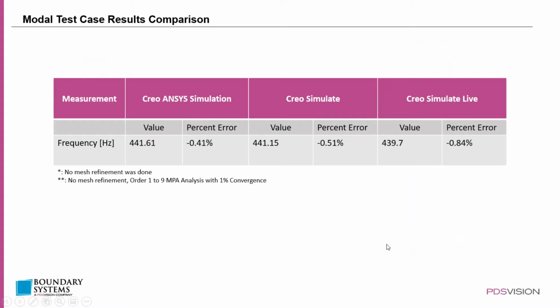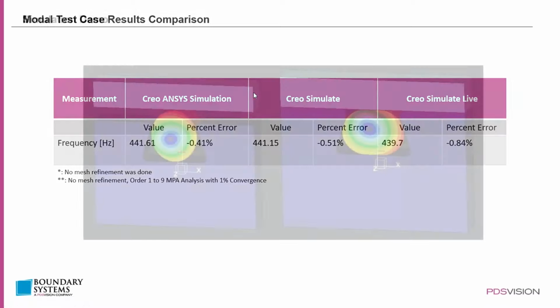And here, what we actually interestingly enough see is every software is very accurate at calculating this modal frequency, which points to the fact that for modal analyses, if you're working within the first 6 modes, you can be pretty confident in any of these softwares because modal analysis overall is a pretty idealistic calculation. We're calculating eigenvalues and things of that nature. So these are all pretty good softwares if you are working with modal analyses.